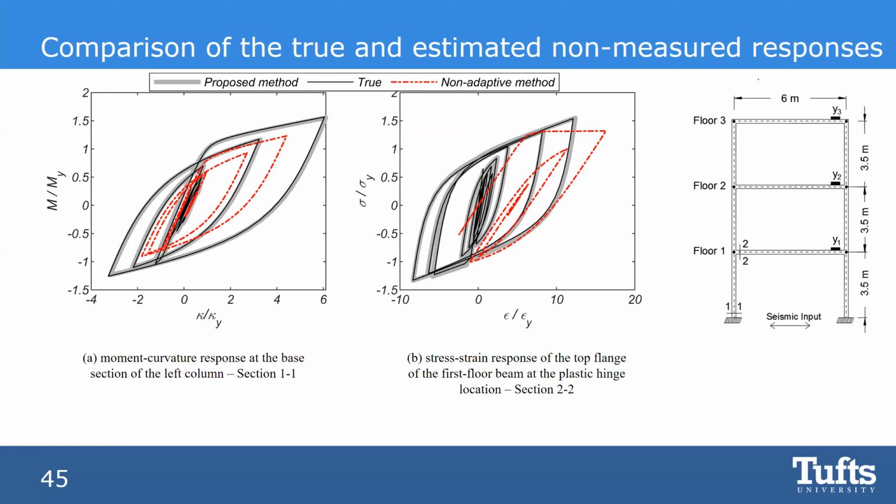But when you go and do prediction of the non-measured response, like the stress-strain response history or other things, the one that just matched the response and couldn't get the parameters of the model obviously does a bad job. Again, this is only true when your noise properties or modeling error properties are time variant, which is the case for every single structure when you look at long times. Within an hour, you probably don't have your modeling error change. But within a season, yes, you do. If you look at a wind turbine, maybe within an hour it changes too.